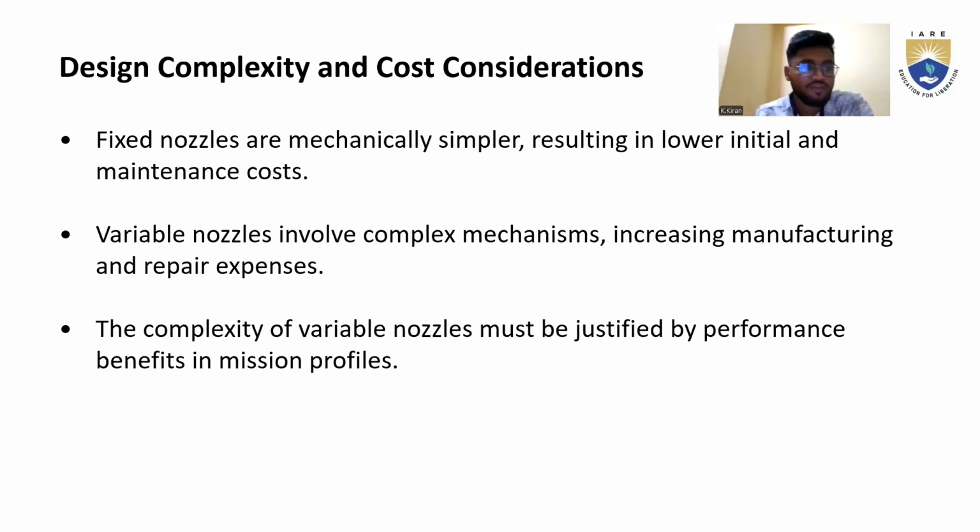Now, design complexity and cost considerations. Fixed nozzles are mechanically simpler, resulting in lower initial and maintenance costs. Variable nozzles involve complex mechanisms, increasing manufacturing and repair expense. The complexity of variable nozzles must be justified by performance benefits in mission profiles.